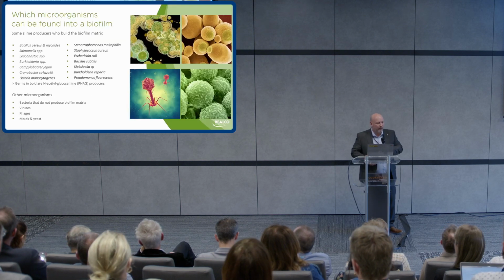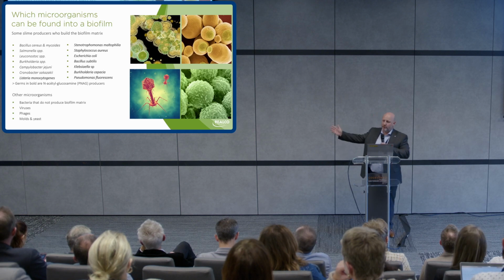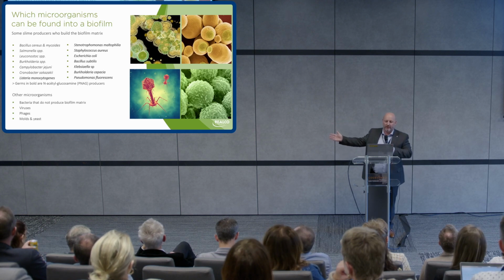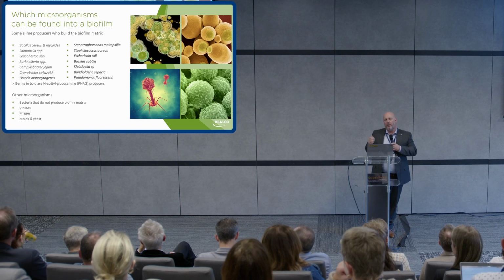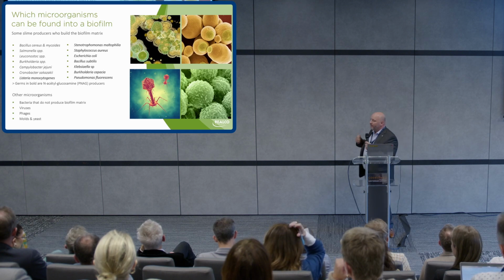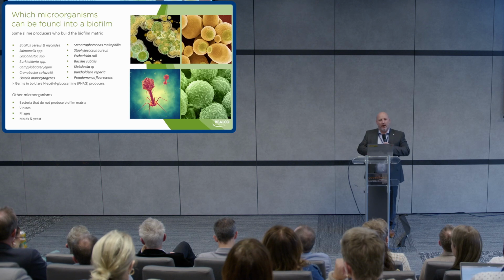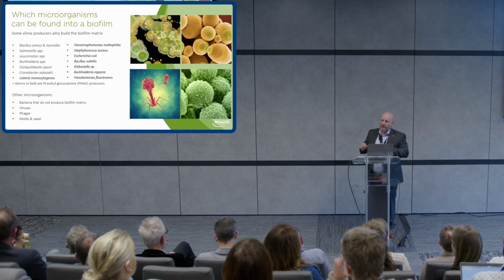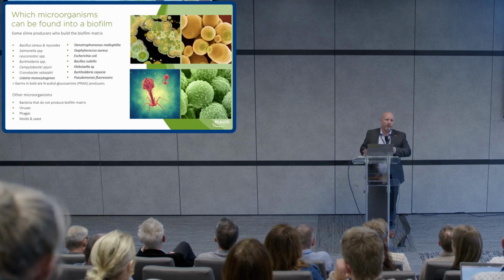When we talk about biofilms, many germs are capable of producing biofilm. You can see those ones. You know them. They are present in the dairy industry. It's also important to understand that the ones in bold are capable of producing a very specific and tough polysaccharide, what we call PNAG. The PNAG is very difficult to eradicate with standard solutions, and even with enzymes. You have to use very new enzymes that are now on the market to deal with the PNAG protection.